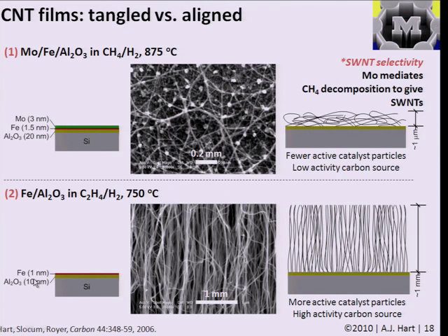In the case of carbon nanotube growth, one way to make a network is just to put the catalyst onto the substrate. By different growth conditions, we saw that we could grow a tangled film or an aligned film. In the case of the conditions that give a tangled film where the nanotube density is lower, this would be a way to produce a network of tubes on the substrate.